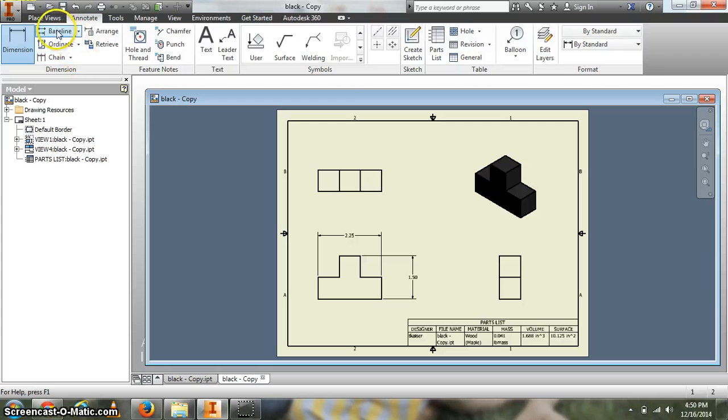Next thing we can do is we can add a baseline dimension from here to there, to there, continue, and drag those out, and you can see the difference between those two, baseline versus initial. Now, if you like the way the baseline looks, and you like the information it gives you, you can escape, get rid of it, leave it, up to you. Let's get rid of these two basic dimensions, and let's do some baseline dimensions.